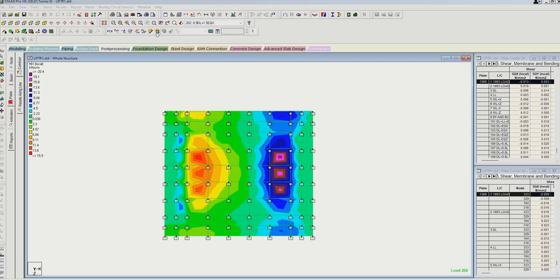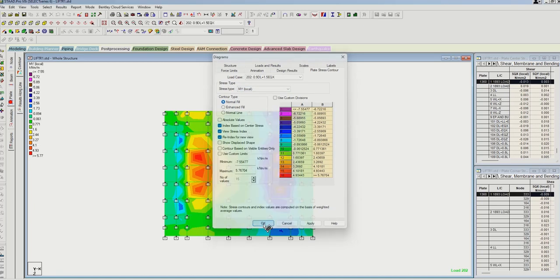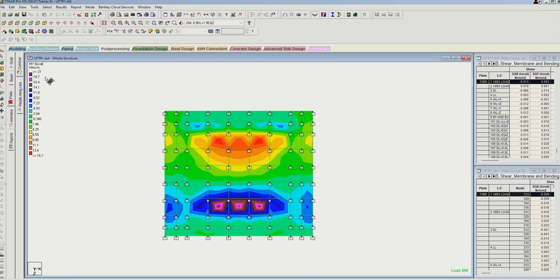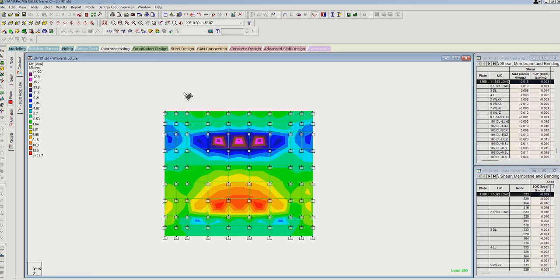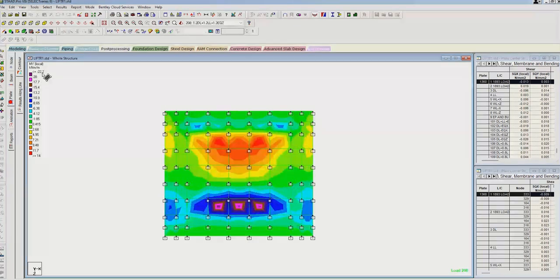Similarly, we can find the design moment about y direction, and I can just have a look at what the design moment can be. Here you can see minus 21. So the maximum design moment is going to be 22.2, which is being governed by this load.